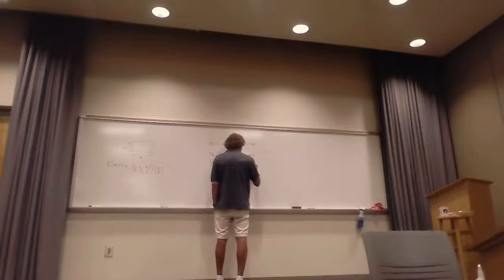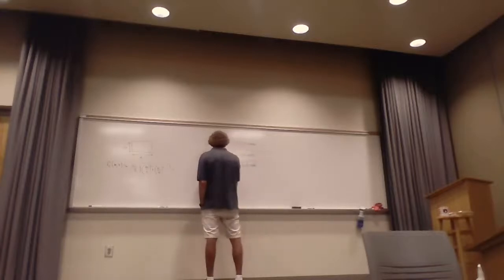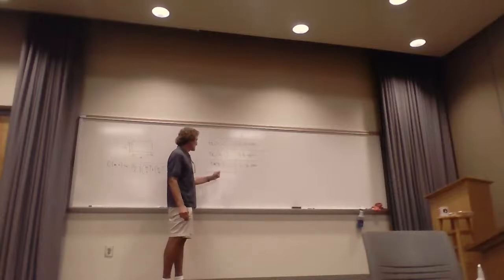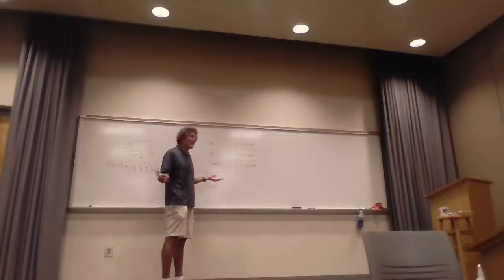11.8 gigahertz. And finally, the last one, by the way, some people just put TE11, they put it in TM11. You got full credit for that. All right, that was 4 frequencies, even though there's a double right there. The 1-1 mode's got both E and M modes.